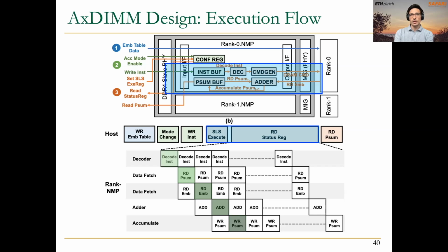During that time, the CPU as well is checking all the time this status register, which is one of the configuration registers, and that is the way for the near memory processing unit to signal the host processor when the execution of the near memory processing kernel has finished and all these instructions have been executed.